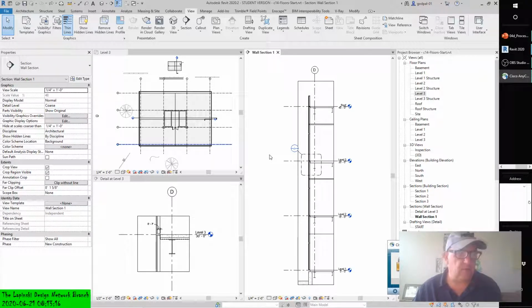One easy way to accomplish this is to use the cantilever option when you are creating or editing the boundary lines of the floor. If you're using a floor type that includes a structural deck layer, select any of the boundary lines and you will see cantilever settings in the options bar. If you define the boundary line at the center line of the supporting member, define the cantilever value for the steel to be 0 and concrete to be the value appropriate to your engineered design. Sometimes these values may need to be negative distances to achieve the desired cantilever condition. When you finish the sketch and observe the slab edge in the section view, you will see a more accurate representation of the appropriate construction technique for the floor element.